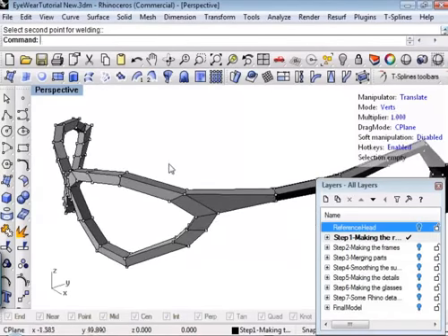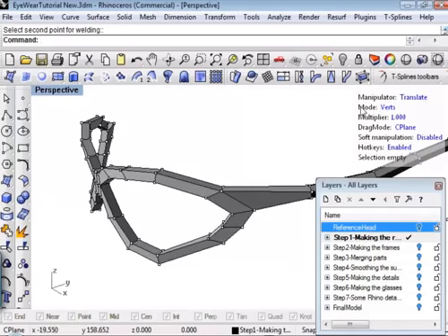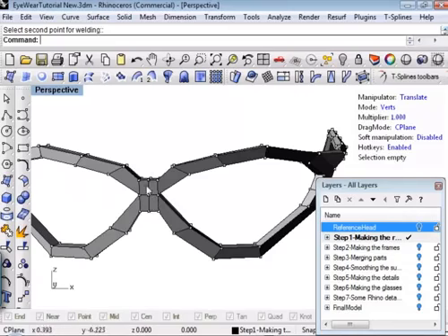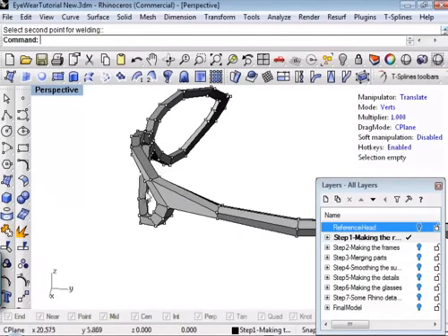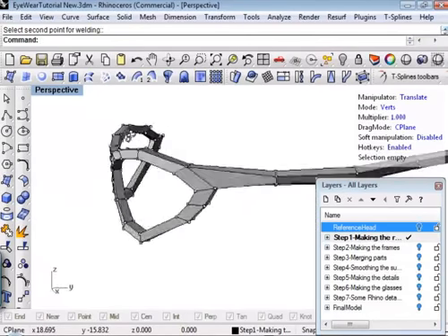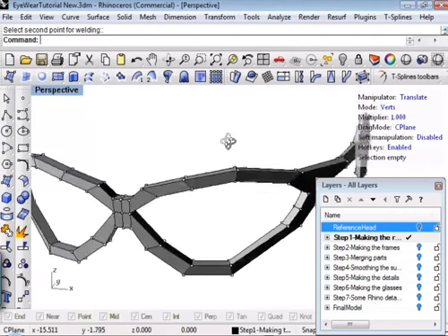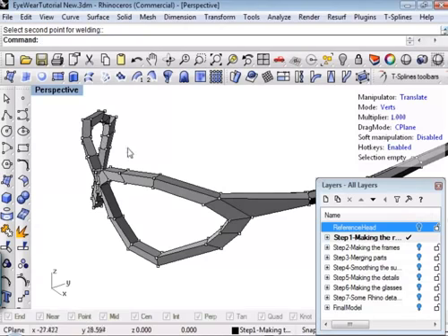And if I toggle smooth at this point, you'll notice a couple of things that have happened. My green symmetry line has disappeared because I blew a hole in this over here. So I lost my symmetry. Actually, I take that back. I welded a piece of geometry that was on this side to here. There was no geometry over here to mirror it to. So I have a hole over here that's not welded to anything. This temple was not symmetrical. So what happened was T Splines lost my symmetry.